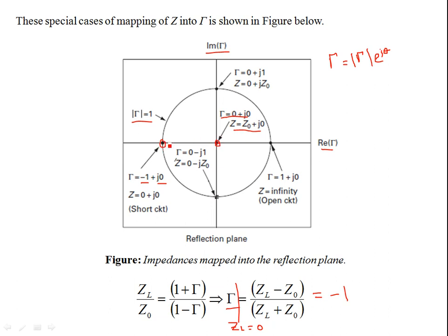Okay, so you see with the gamma we have the impedance transformation as well. So there is a one-to-one mapping. You must understand from the complex gamma plane how you are transforming between z and gamma. If you specify gamma, you can specify the z as well. This point is your natural impedance of the transmission line. This point, for example, shows a short circuit. So gamma equal to minus 1 shows a short circuit.